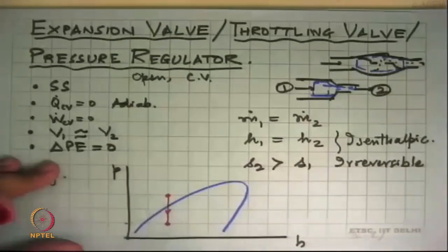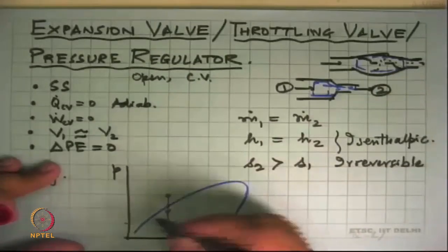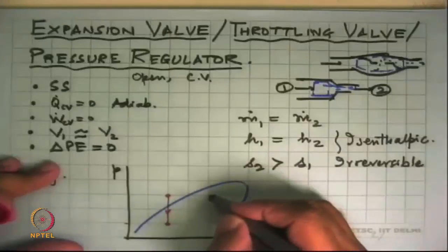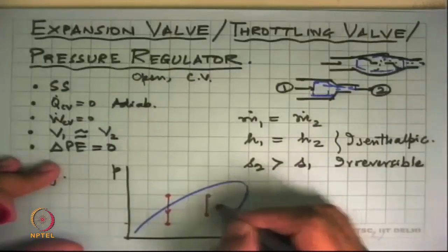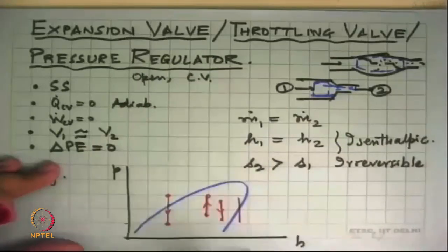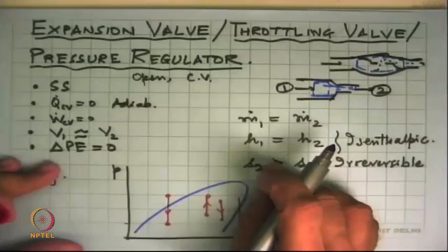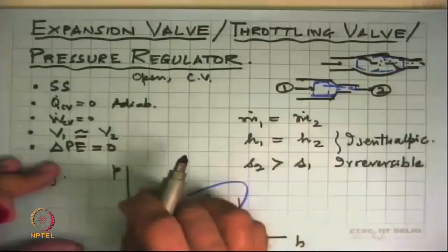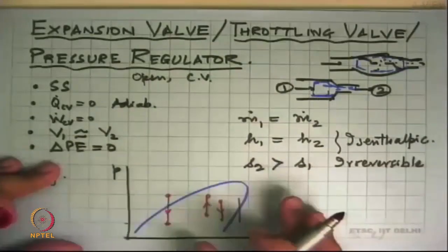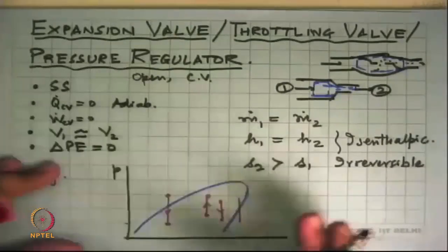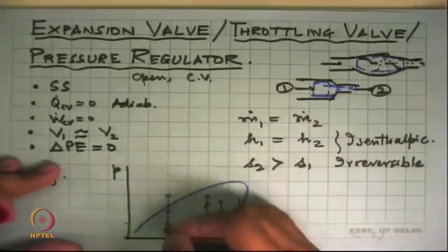And as we saw with turbines, in general and pumps, we do not want any work producing device that operates like this or like this or there or there. We want work producing devices to either handle only a vapor or a gas or only handle a liquid, not mixtures of these two. Such machines cannot be made. Okay, so in the refrigerator, we cannot put a turbine.